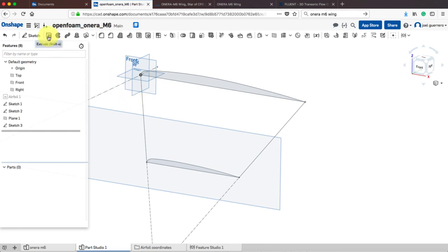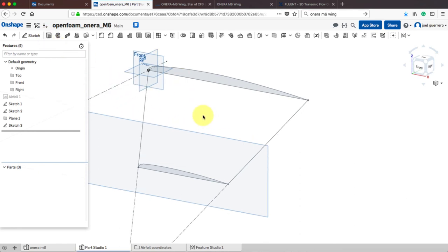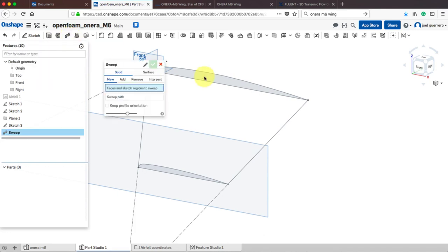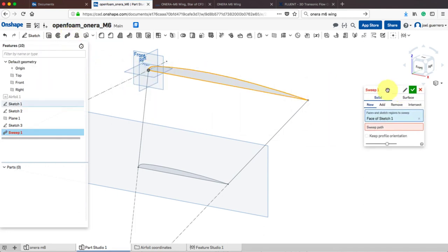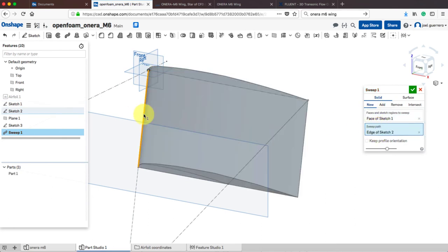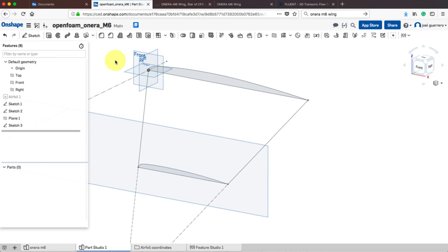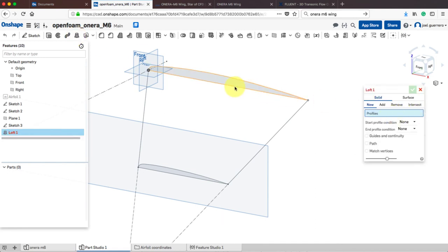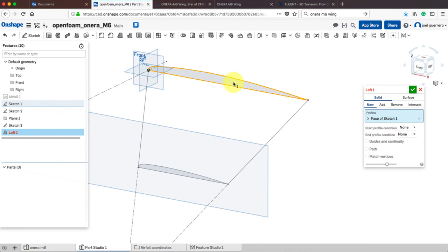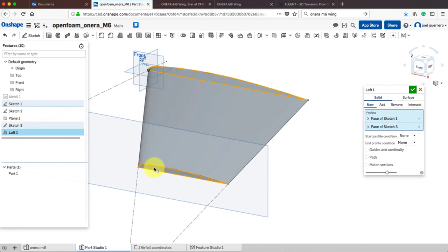We have seen extrude, but we cannot use it here because extrude is just linear extrusions. Revolve, we answered about revolve. Sweep basically will take this face and you will choose a sweep path. But what we want to do is go from this face to this face. And the tool to do that is this one, the loft. This is the most powerful tool, it lets you create basically any kind of geometry. So we choose the airfoils as the sections. We have two sections. You can have many sections, okay?